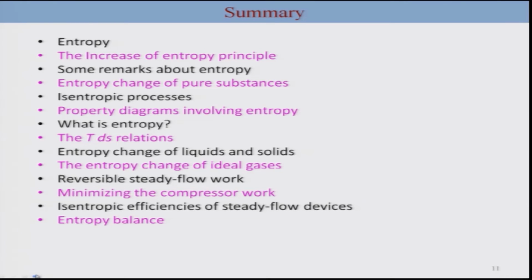So we have looked into the definition of entropy, understood the increase of entropy principle, which means entropy is generated and all the time it increases, if not remains constant. We made remarks on entropy in terms of the reasons for irreversibility. We talked about entropy change of pure substances and the isentropic process where entropy is constant, and property diagrams such as the h-s diagram, where it becomes very useful to describe the process where entropy is involved. We also looked into the molecular behavior of entropy, the T dS relations in terms of internal energy changes or enthalpy changes, and entropy change for liquids and solids,